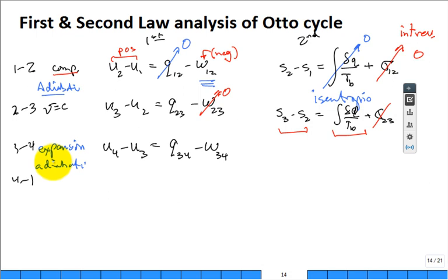Now, if you really want an accurate simulation and you have a lot of computer code power, well, then you can model the heat transfer. And when you take ME 4313, you will be given the tools, if you choose to use them, to actually do a pretty good approximation of analyzing that. But you're going to need to know how long it takes to go from top dead center to bottom dead center, what the cylinder wall temperature is, and what my gas properties, speeds and conditions in that cylinder are. So it's not a trivial problem. It's a pretty complex problem.